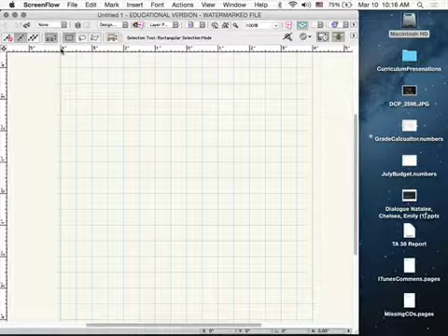Okay? First tool is the line tool. Looks like this. If you mouse over it and hold, it says line. The quick key for it is 2. Okay? Draw a line. We have several modes up here. We're in unconstrained line. That's probably the easiest one to work in.